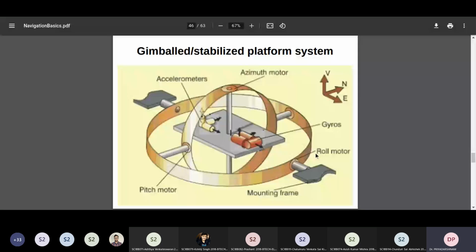This is called servoing. You might have heard of servo motors, no? Servoing basically means keeping the position the same even when other things are changing, by looking at the small errors in the motion and compensating by going back to the zero position, whatever that initial zero position is.